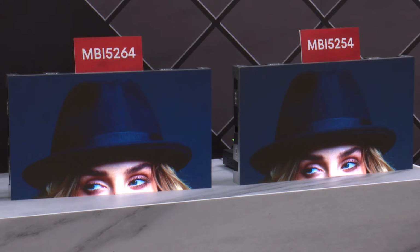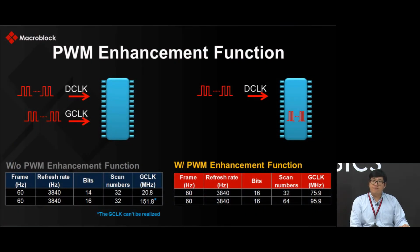Of course. The key of the HDR-Optimized technology is the PWM enhancement function. And how to reach the 16-bit design, here is an example. In the 32-scan design with 4K Hz visual refresh rate, it requires the grayscale clock at 151.8 MHz. And it is really difficult in the board design. And with the PWM enhancement function, the grayscale clock will be down to 95.9 MHz, and the 16-bit can be realized in the LED display.